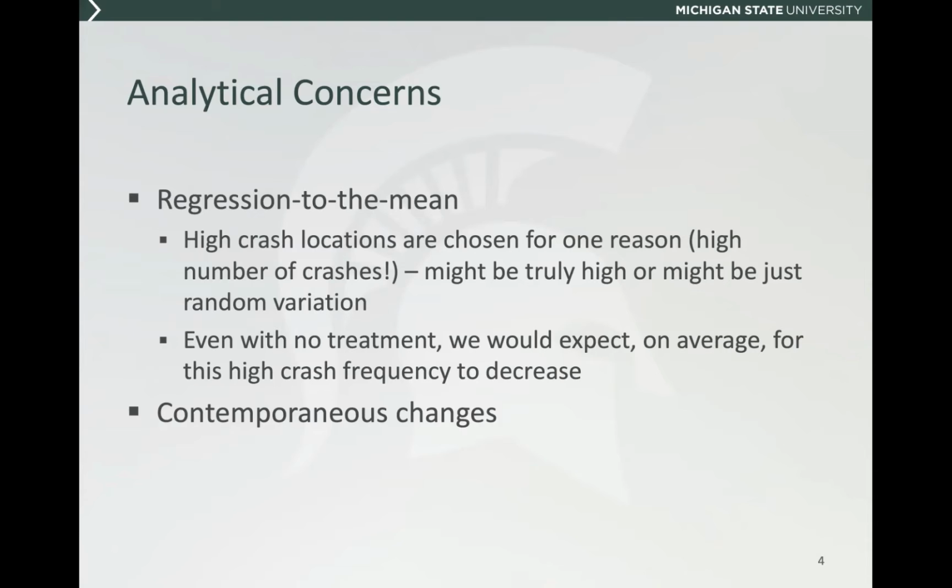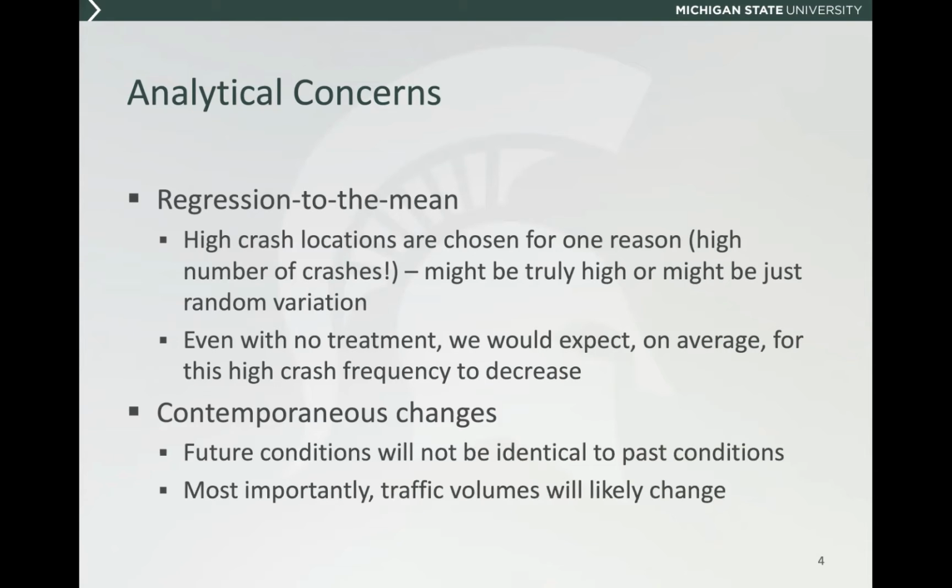Now, there are also some additional concerns that may come into play, and that would relate to contemporaneous changes. What we mean by that is, once that treatment is implemented, there may be some other differences that occur concurrently that weren't present during the pre-implementation period. As an example, here in Michigan, if we go back to December of 2019, we had legalized recreational marijuana at that point. If that has safety impacts, that fact would be lost on us if we were conducting an evaluation of crash data for 3 years prior to a project that was implemented in 2019 or 2020 versus 3 years afterwards. Similarly, if we're in the midst of a pandemic, it's probably not an apples to apples comparison as well.